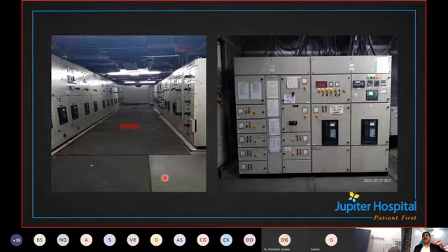Now, if something happens to that air circuit breaker or MCCB of maybe 1250 ampere or maybe 2500 ampere, it is a near nightmare, because you cannot do it. It's not so easy that you can pull the cable from one thing and put it in another. It's not practically possible. So whoever is going to design this has to make sure that there is always a left side and right side panel where we have sufficient MCCBs available, so that if there is an issue on the left side, I can switch over to the right side and do the servicing.